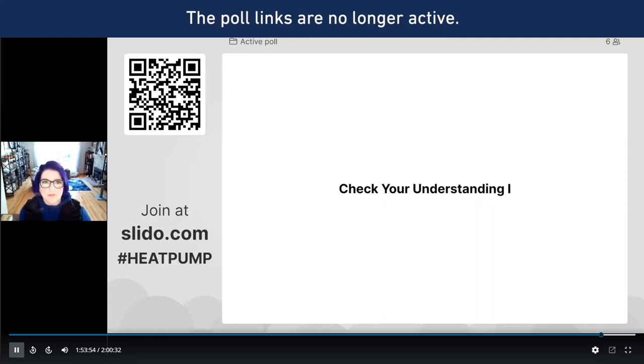Now, if that system was an air conditioning system slash heat pump and you were in cooling mode, you definitely would have a lot of heat coming off of those systems. But that is not something that you would find uncommon anywhere. It's just heat being rejected to the ambient space. So it's quite okay. But in the reverse, just know if you were to put your hand over those systems in heating mode, that airflow coming out would be cold. And that doesn't really happen with domestic hot water heat pumps, right? We're never going to take hot water and cool it down. So that is mostly for comfort heating and cooling applications. Absolutely.